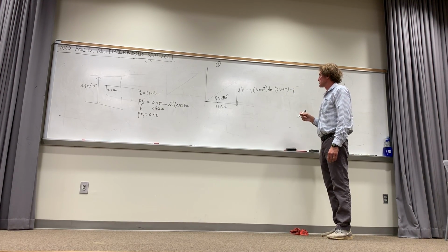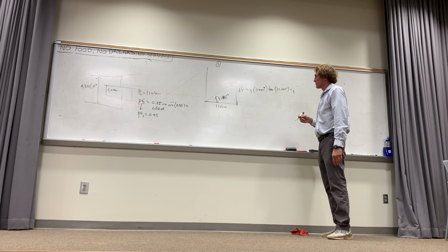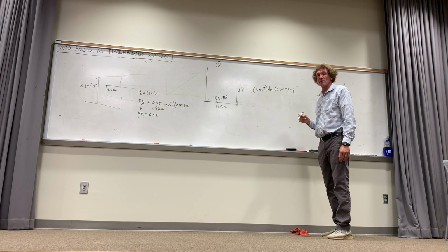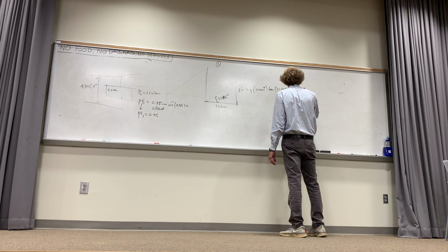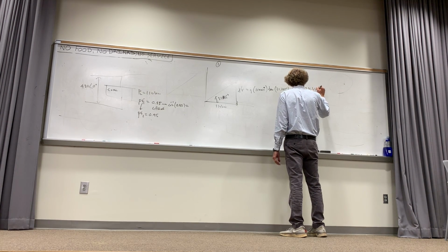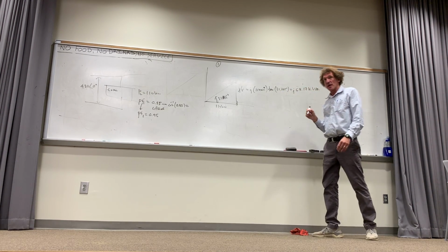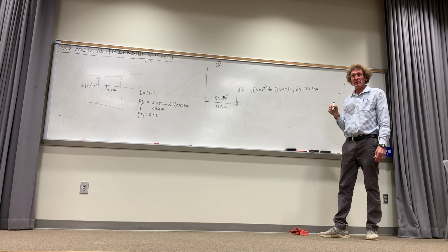Just take the tangent of 31.785 and multiply it by 110 times 10 to the third. What is Q? 68.17. So it's J68.17, and that would be kVAR. Just keep watching, you're going to see how this is done.